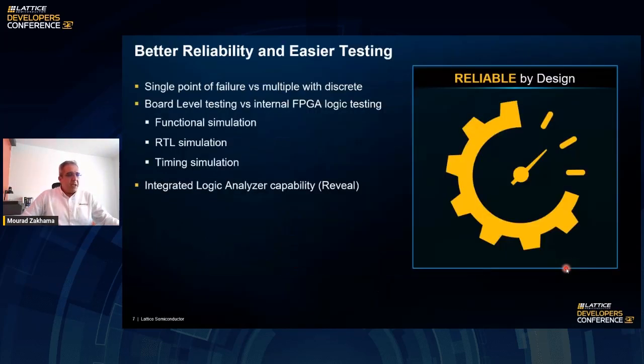So reliability is another aspect, and testability. Without going through a lot of details in terms of the reliability, when using an FPGA, you have a single point of failure. There are multiple points of failure with discrete components. This also has a ripple effect on testability of the design. In fact, you can perform more thorough testing of the functionality that you integrate in the device, and you can do it at different stages of the design.